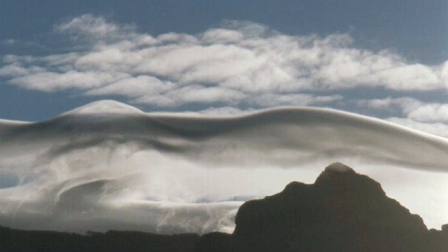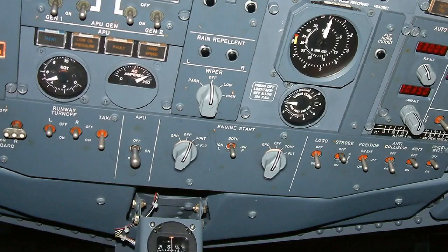Heavy in-flight turbulence can seriously disrupt the airflow into the engines. Using the correct turbulence penetration speed will reduce the possibility of compressor malfunction. It may also be a requirement of the checklist in these conditions to activate the continuous ignition system to reduce the probability of engine flameout.